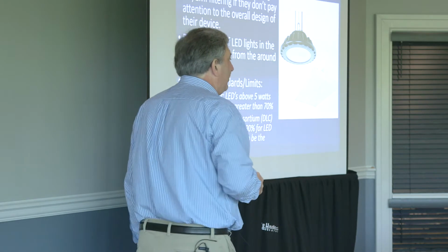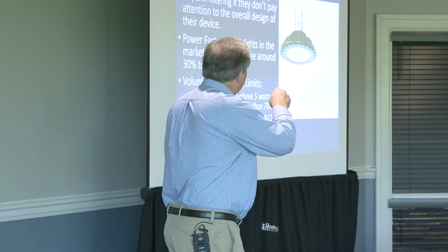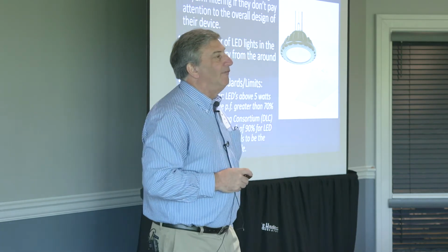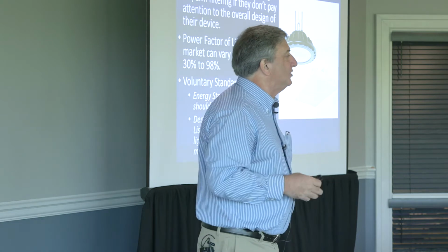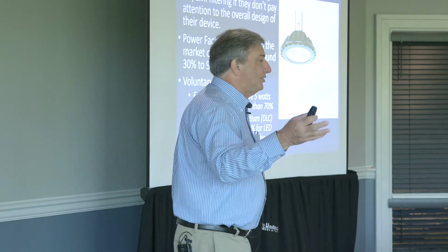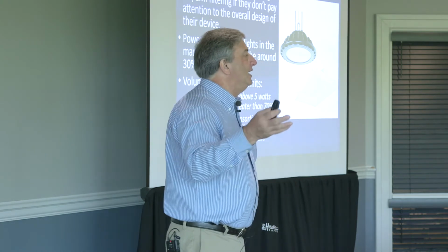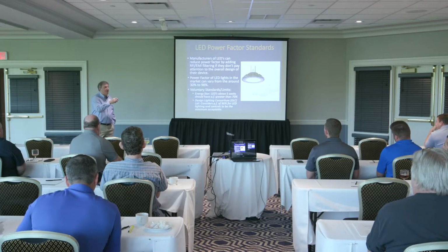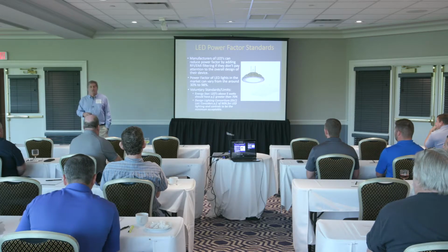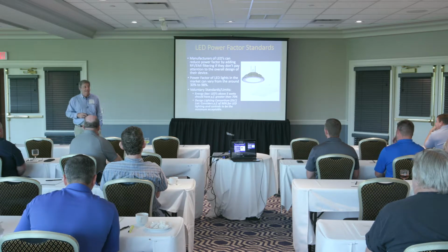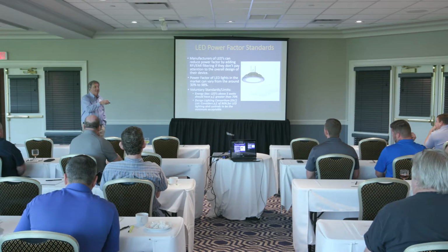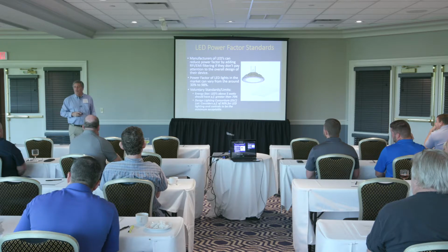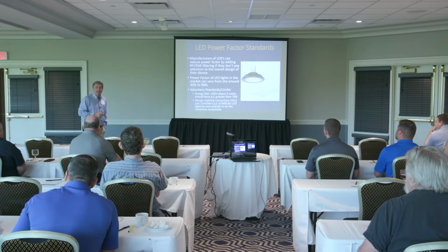Very common for that noise coming off the LED to interfere with my FM communication system, my wireless system, things of that nature in the plant. And so manufacturers started putting noise filtering into their LEDs, and if they're not careful in that process, they can drop the power factor significantly. That's really what's going on in the market today.